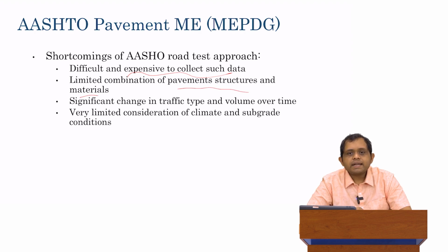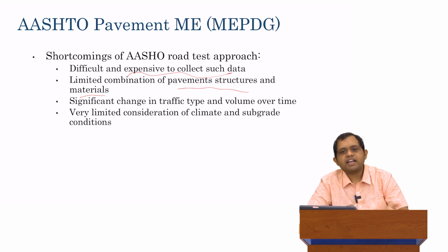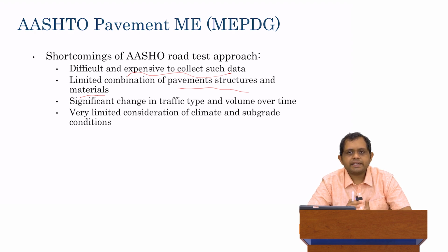The number of different types of rigid pavement materials that we have today, well, there are different types of cements, but then we also have different types of supplementary cementitious materials, fly ash, silica fume, etc. And different varieties of combinations for aggregates, for example. We have virgin aggregates, recycled aggregates, and some byproduct aggregates, etc. The variety of combinations that we have today in terms of materials for rigid pavements is so high that it is basically impossible to check all of them within a given road section.